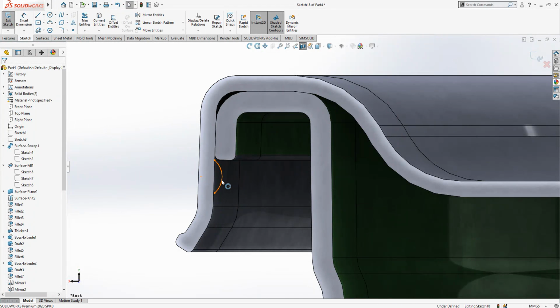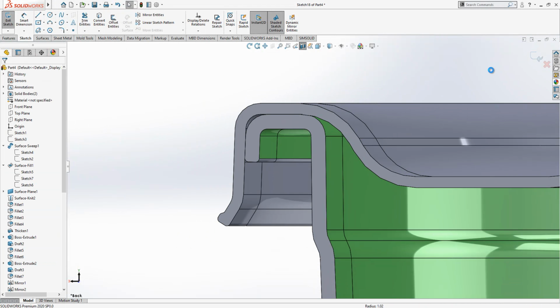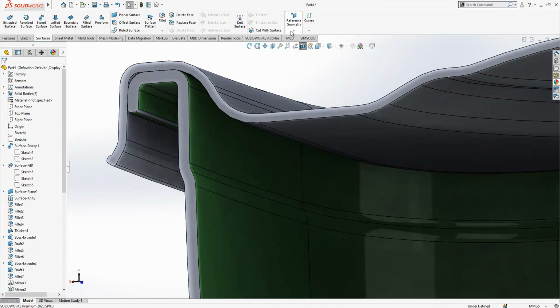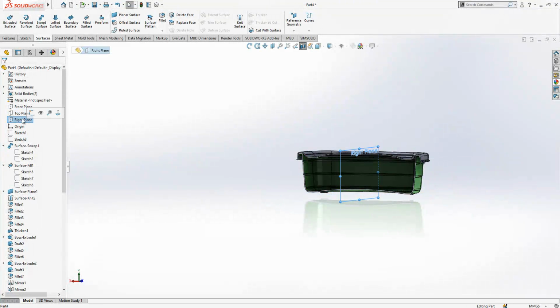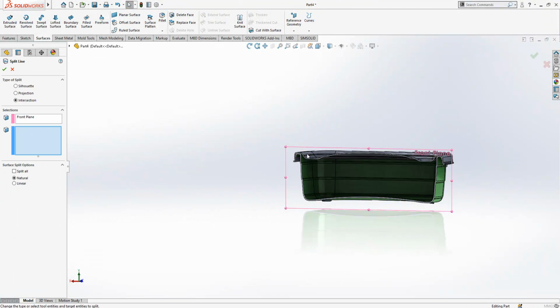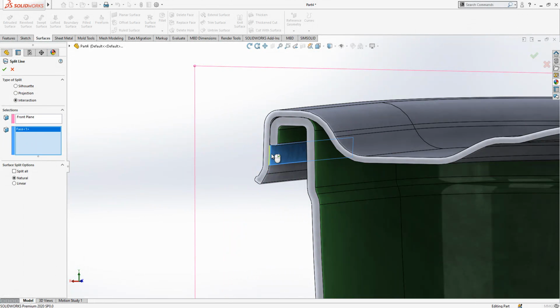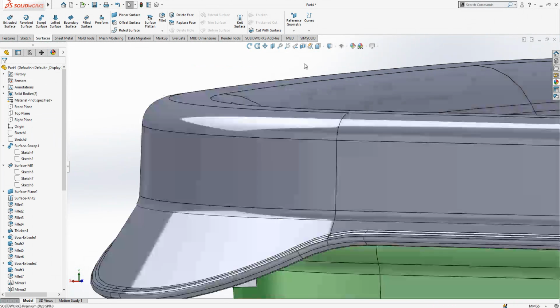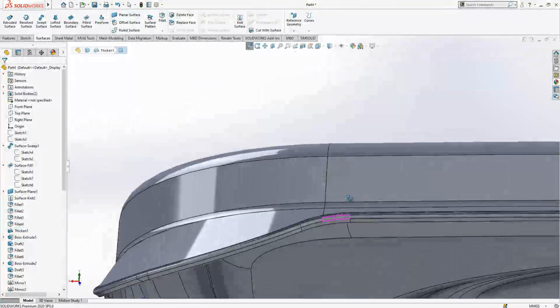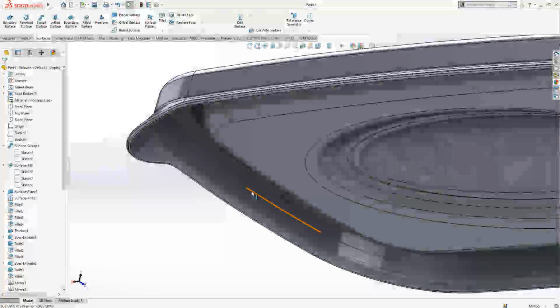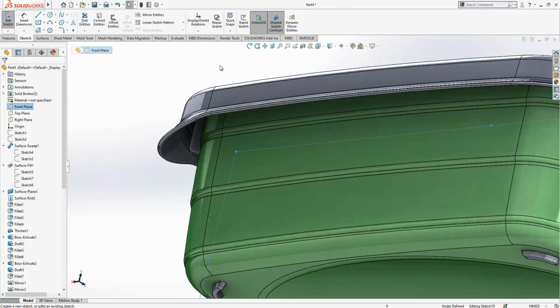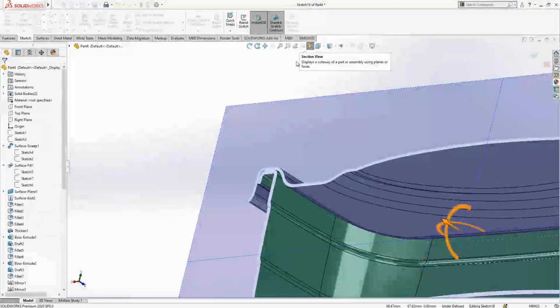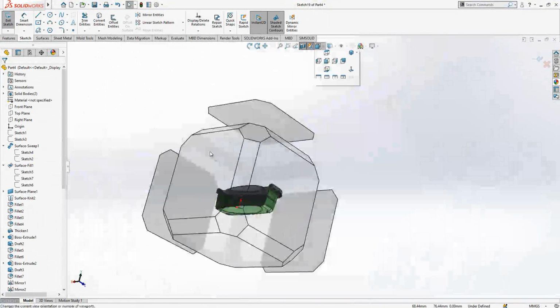And what I'm going to do now, guys, create another thing. We need some extra object here. I wanna select my right top plane, split line, and then break this edge as well. So if you look, let's hide it. To break here and here is good. Everything comes back from plane sketch, and then we activate our section view, and then we look normal to.